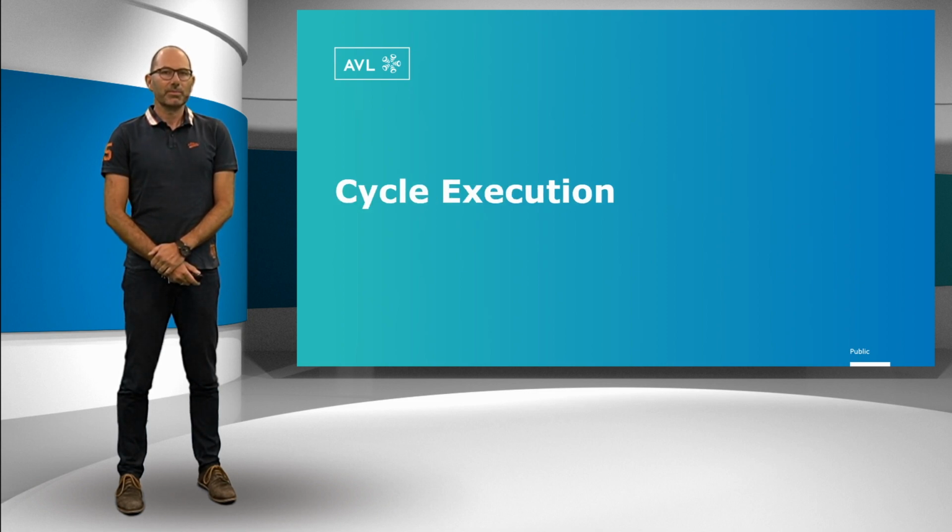The cycle execution with CAMEO is system independent. It doesn't work only with Puma, it works with any compatible automation system. But not only with automation systems. Cycles can also be executed at your HiL or SiL system. In addition, the cycle execution is not limited to one single system. You can execute cycles with tracks from different systems. The execution frequency can be up to 100 Hz, and the length of the cycle and the number of tracks is only limited by a maximum test size of 2 GB.